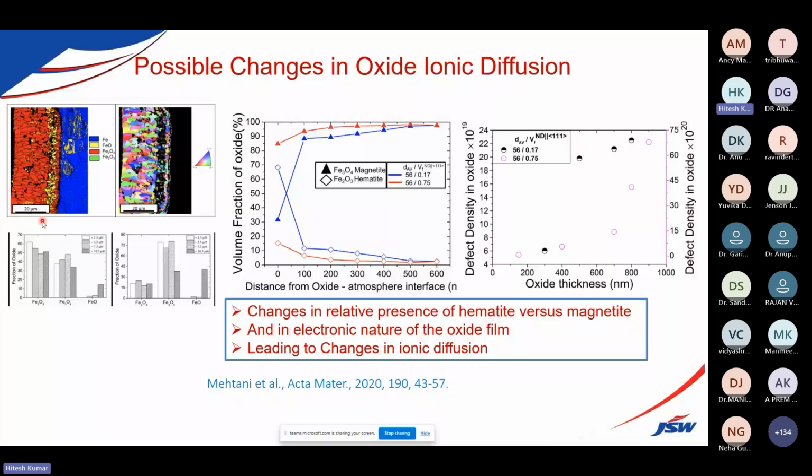So with a more complex structure, the porosity is less, and this will improve the oxidation kinetics. If you have a material with a gamma fiber, the material is more oxidation prone, but otherwise the material is less oxidation prone. This is also confirmed with the help of defect density as well as the volume fraction of oxide. XPS also confirmed the data which we calculated with the help of XRD. XRD gives you the phase fraction as well as texture results and stress analysis. For phase fraction analysis we use HighScore.